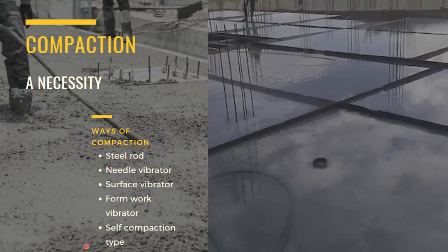What is membrane curing? Curing compound may be used in line with moist curing. It is also applied to all exposed surfaces of the concrete as soon as possible after the concrete has set. It prevents evaporation of concrete water content. It is nothing but membrane curing.